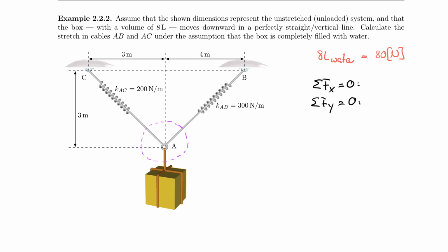In other words, if there was another spring or another cable, let's say I have another spring here, then this would not work because I also cut the spring here, and I would end up with 1, 2, 3 unknowns, and therefore my 2 conditions would not be enough anymore. And you could say, what is with the sum of the forces in the z direction? Then I have a third condition.